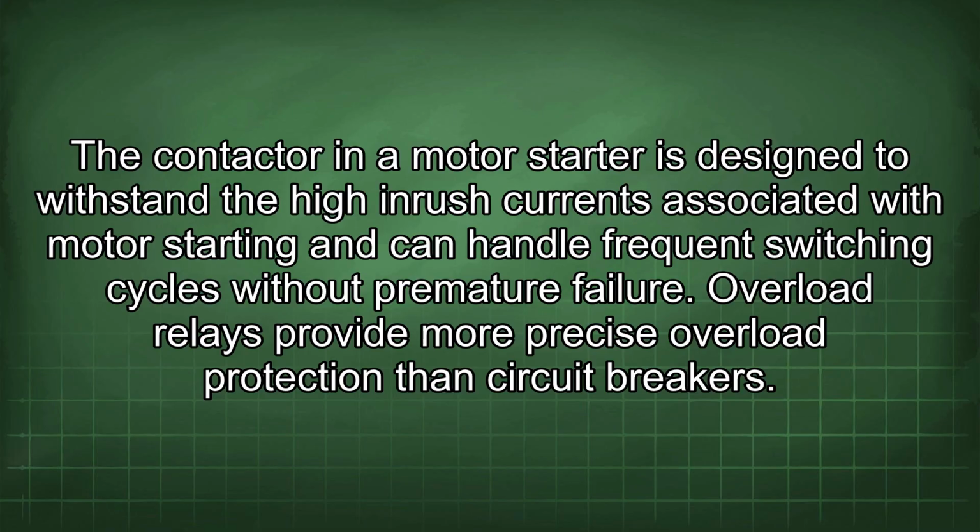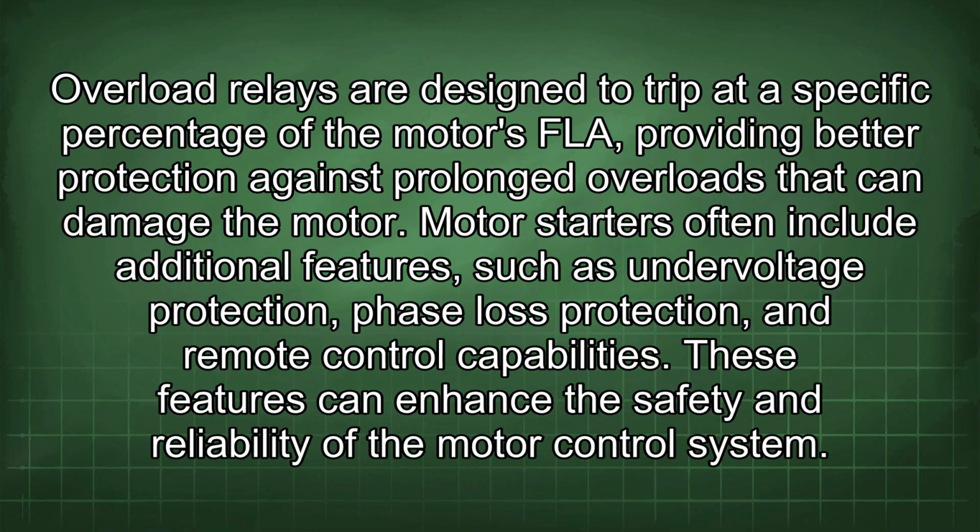Overload relays provide more precise overload protection than circuit breakers. Overload relays are designed to trip at a specific percentage of the motor's FLA, providing better protection against prolonged overloads that can damage the motor. Motor starters often include additional features, such as undervoltage protection, phase loss protection, and remote control capabilities. These features can enhance the safety and reliability of the motor control system.